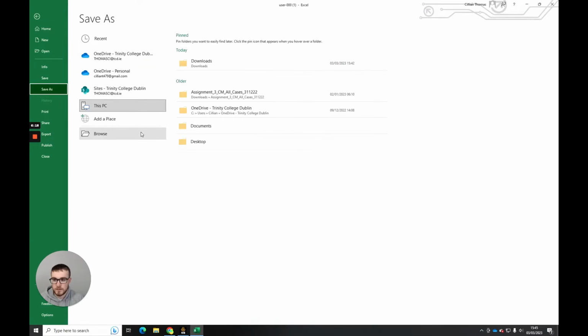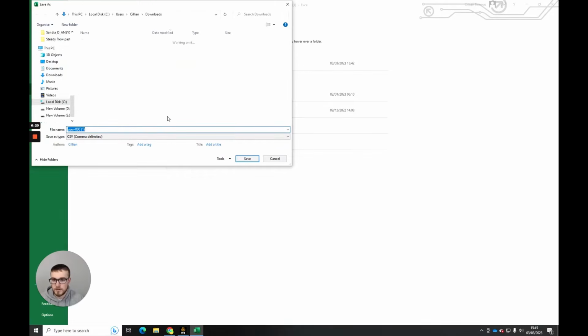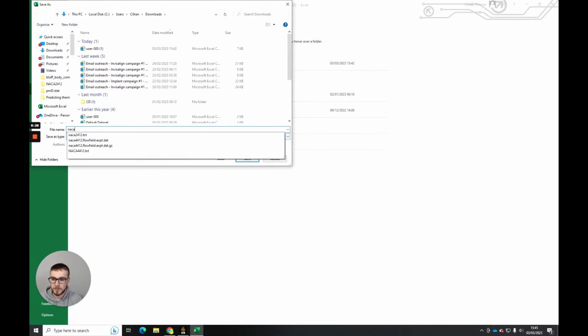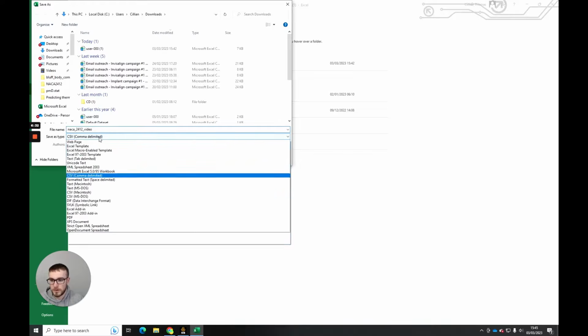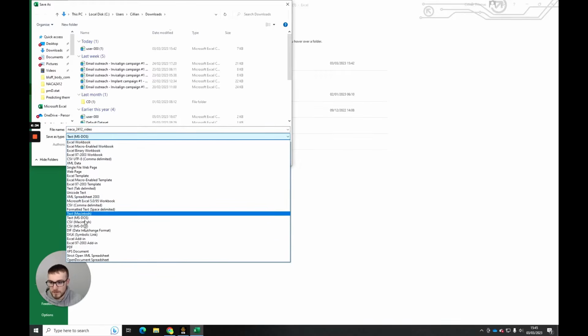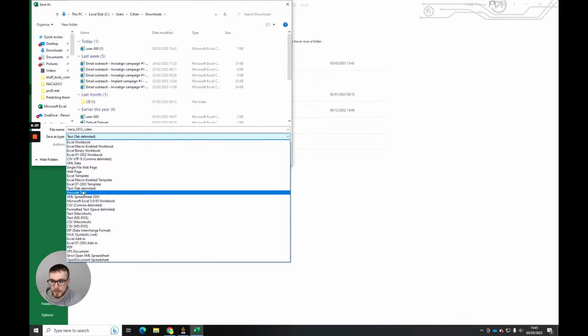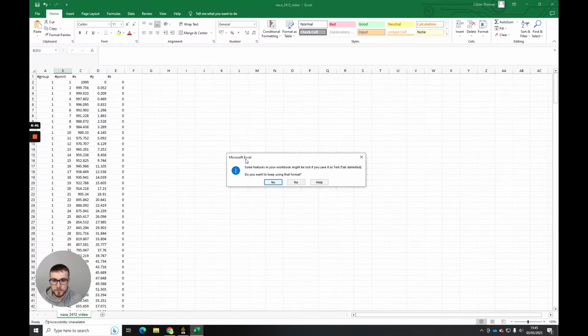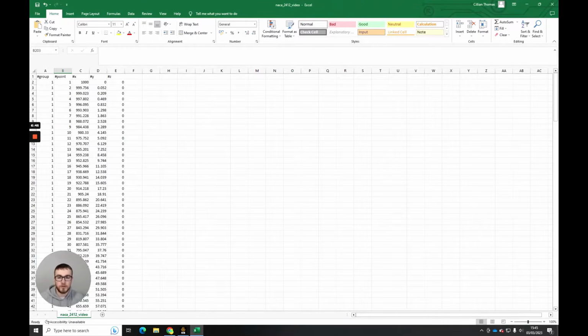So I'm going to save this in my downloads, a very bad practice, but nonetheless, just for video purposes. I'm going to call it NACA2412, and I'm just going to call it a video because I have this file done before. This needs to be a text file in tab delimited format, just like so. And hit save. Yes, that's okay. And our file is now ready to be imported into Design Modeler.